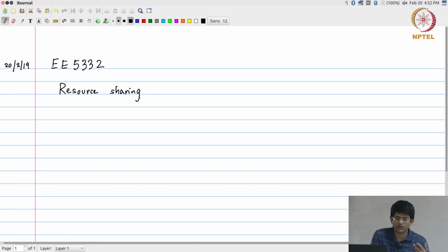Moving on from there we said, if I don't have infinite amounts of hardware, what can I do? I can come up with an analysis which says, assign a single piece of hardware to each functional unit or actor, and then determine the critical path. That critical path in turn determines how long it takes for one iteration of that data flow graph to complete. Once I have done that, comes the question of how do I get my critical path closer to my iteration period bound, or in other words improve the critical path.